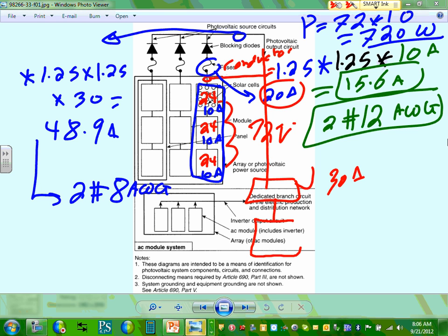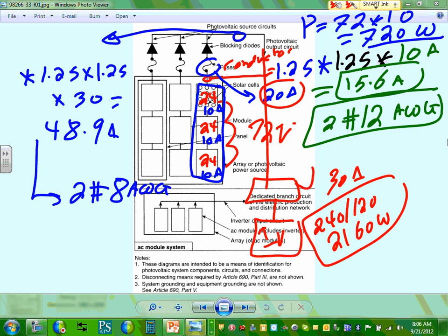Okay, inverter. So I need an inverter. How much power do you need to invert based on my example? 720 times how many? Times 3. We did this math before. 2160. So you need an inverter that inverts to 240 volts slash 120, and I need 2160 watts. So when you go to buy this inverter, you need to tell them I need an inverter that can take me to 240/120 and handle at least 2160 watts. Can I have thumbs up, Chad? We understand? Perfect.